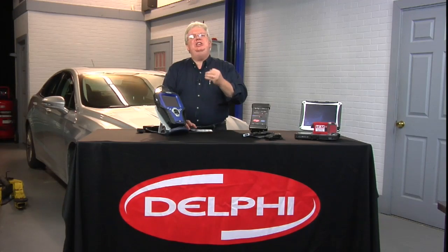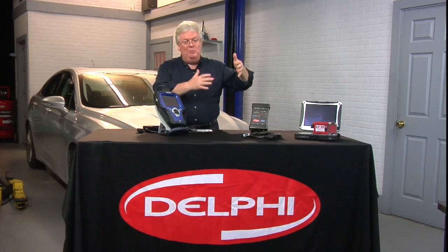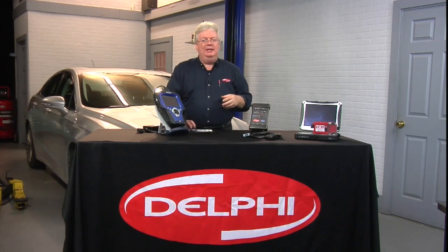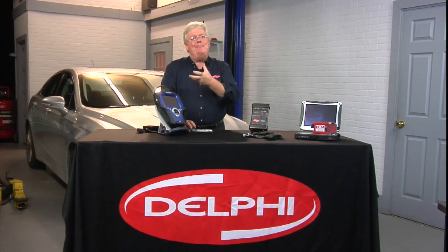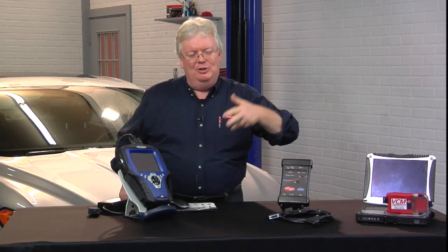But man, when you start seeing decent, believable numbers pop up and the incompletes go away in mode 6, and of course in your readiness page on your scan tool, what gives you the monitor statuses, when they start saying complete, complete, then that definitely is when they finally have recorded the mode 6 information at that particular point in time. So freeze frame data is lost, as we well know. It always asks you, are you sure you want to do this? Because you're going to lose your code and your freeze frame. So that's as well. So the answer is D, as in Delphi.